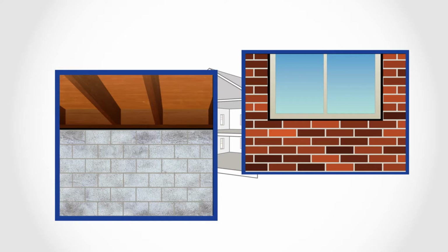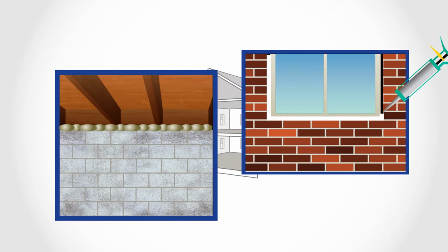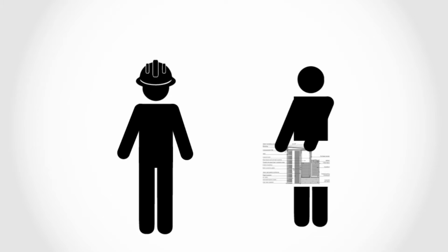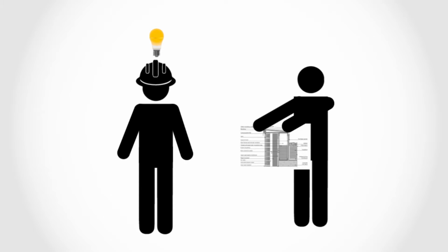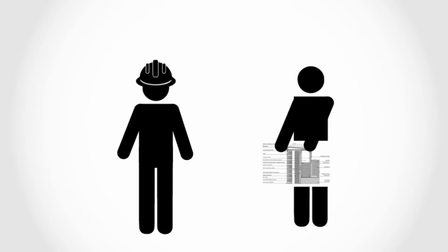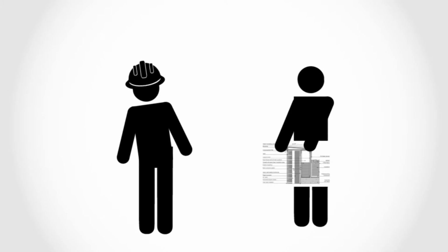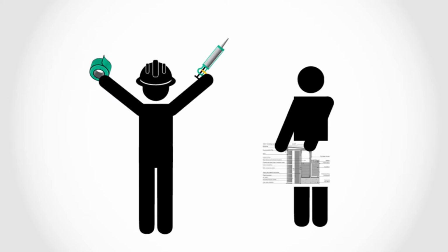The most likely places for gaps to develop in the air barrier are where dissimilar materials meet. The architect will want to be particularly careful to provide air sealing details for these places. Overall, the goal is for the architect to provide enough information in the drawings so that the builder will understand what needs to be sealed at each location. All of this air sealing can be done with conventional materials.